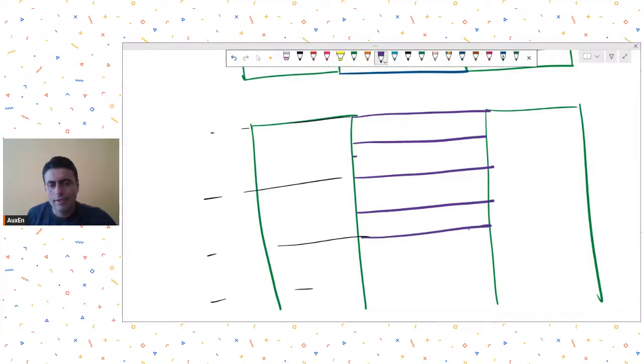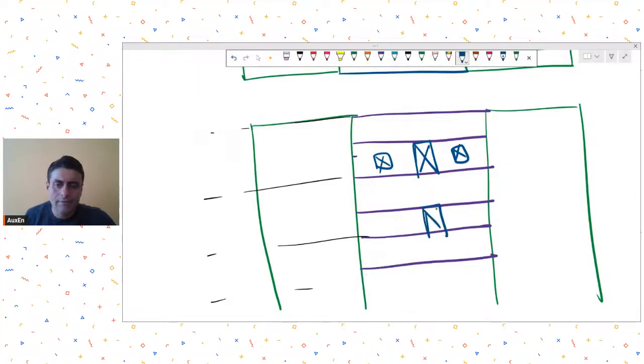Are you with me, following what I'm saying? And maybe here you have planned some door openings. So this is my door opening, this is my window opening. So number one option is that you model everything as a spandrel element. So in that case, you will have to model this entire thing as spandrels and then create openings over here.